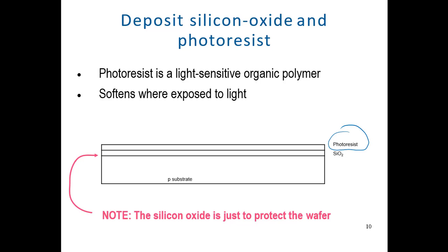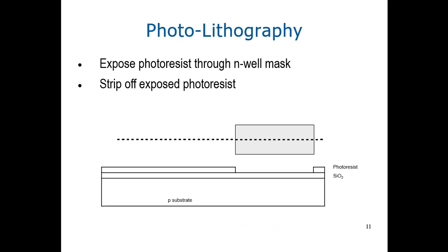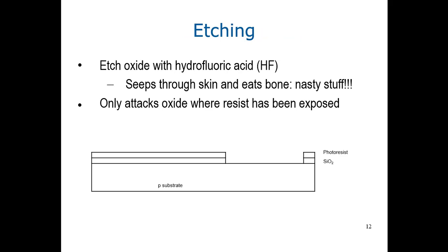And what is the purpose of silicon oxide? It is basically to protect the wafer. And what is the purpose of the photoresist material? It is there to increase the sensitivity of the whole thing to light. Then you are putting your first mask. This is the mask for N-well. What you see is you strip off the photoresist material here, and all the other is the same. So you have applied your first mask and you strip off some region to develop the N-well.